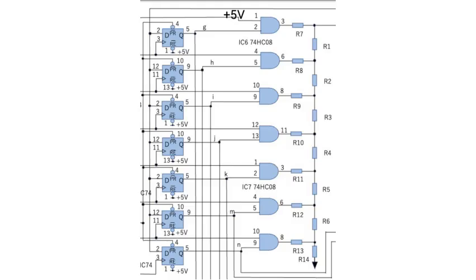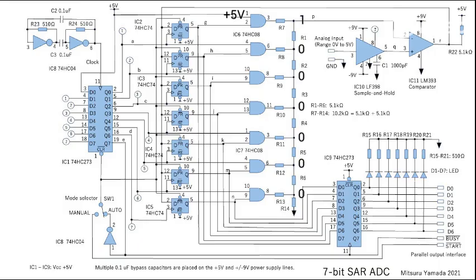Before the first clock tick, the AND gate providing the MSB for the DAC is high, as one input is permanently 5 volts and the other is high from the preset flip-flop. At this point, every output from IC1 is 0, meaning every other AND gate is outputting a 0. This results in the DAC output being Vref over 2, or 2.5 volts.